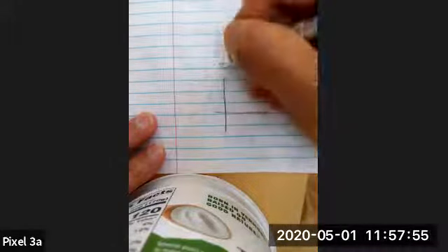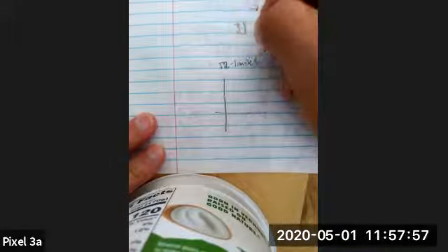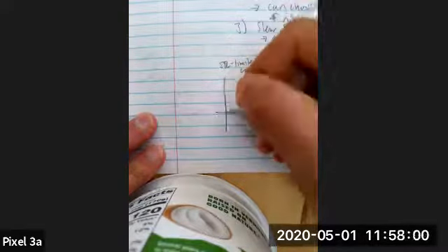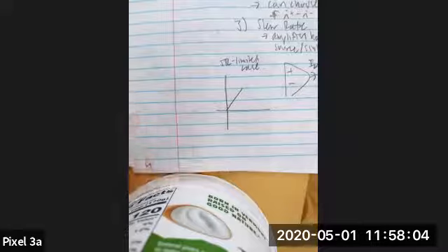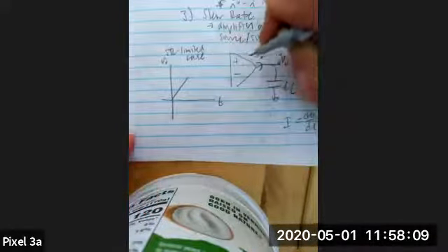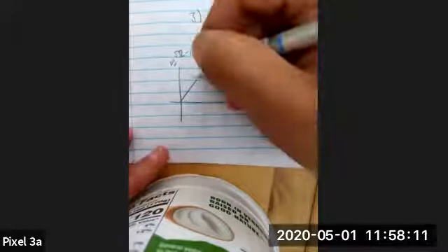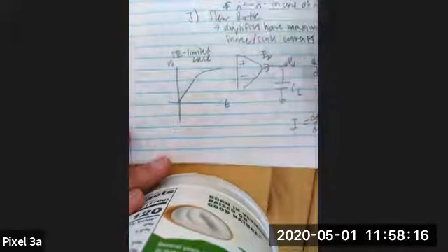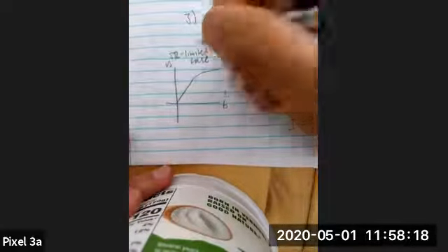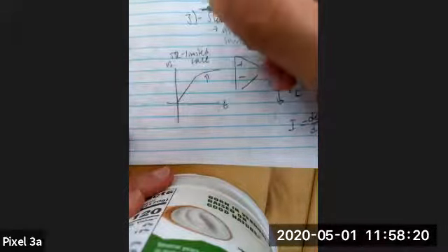So the slew rate limited case is when initially we are just spending a lot of time charging up the capacitor. So the output voltage as a function of time is very linear. And then at some point, which is not really the focus of this class, we'll resort back to what is called a band limited response. This is a bandwidth limited response.